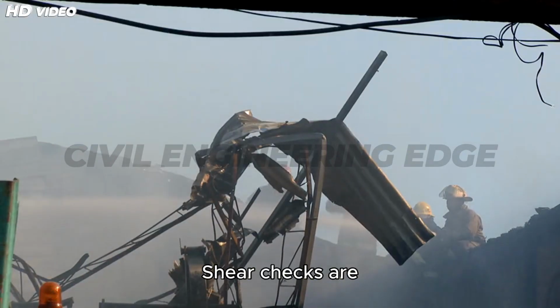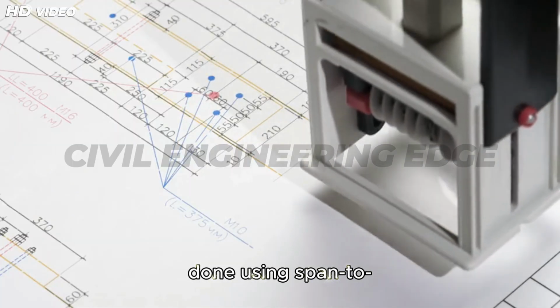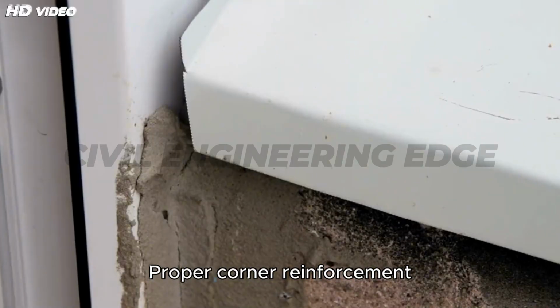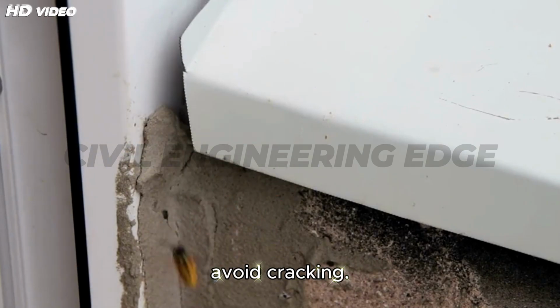Shear checks are essential near supports. Deflection control is done using span-to-depth ratio, modified with stress and reinforcement factors. Proper corner reinforcement is also essential in slabs with restrained corners to avoid cracking.